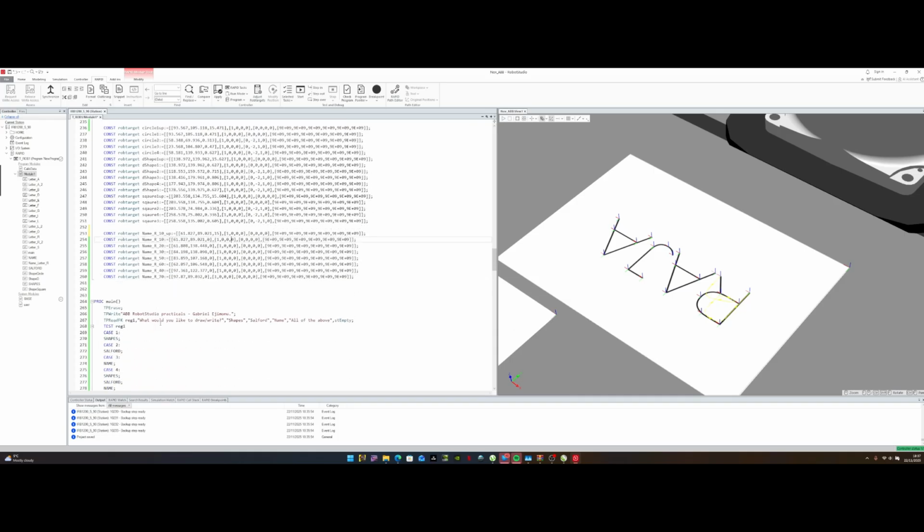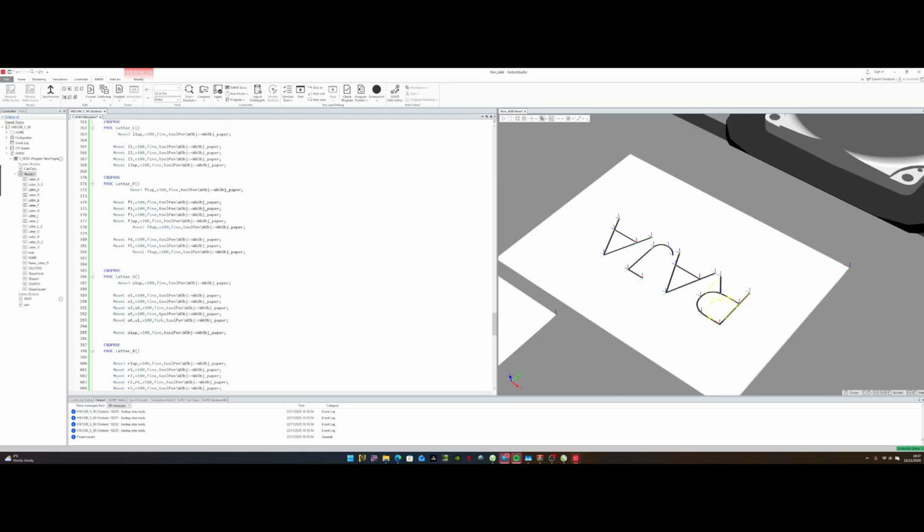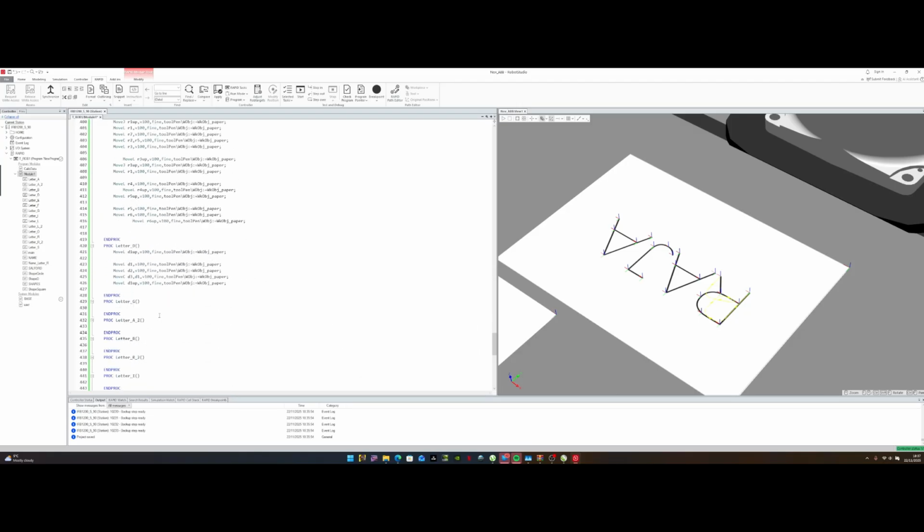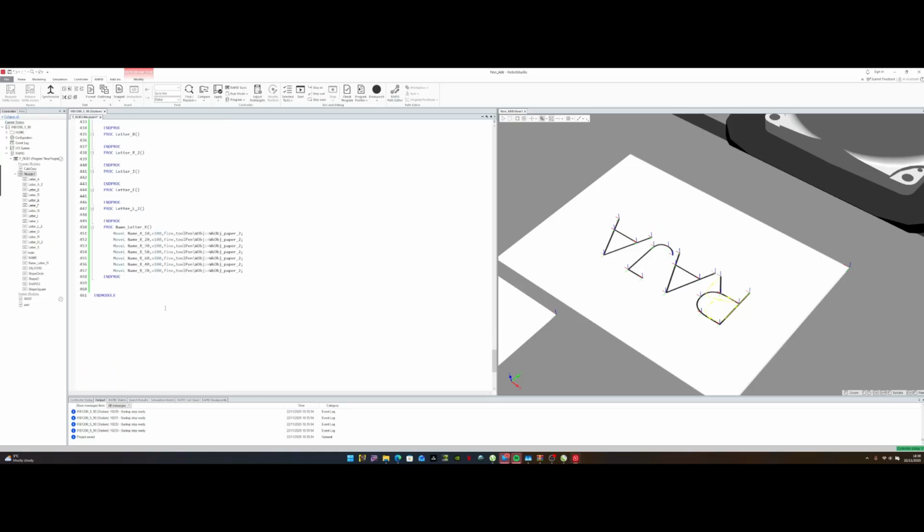Okay, now the first thing I want the robot to do, when he wants to write the name Raja, is to jog the tool over to the top of the first target that I wanted to use to start writing. So I'm going to say Ctrl C here. Just go with me on this. And we're going to use put up here, and I'm going to do a move J, not a move L, a move J, so that the robot can find the most convenient path over there. It doesn't have to do it linearly.